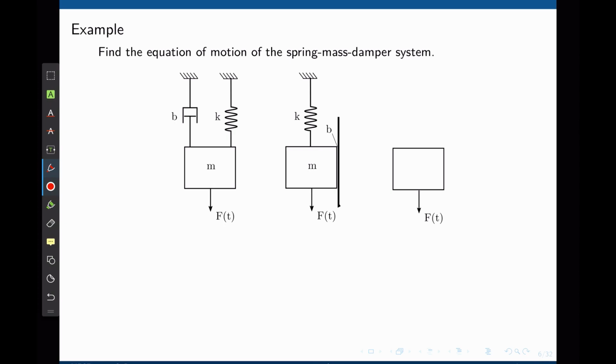The graph on the left is one representation of the viscous friction. The graph in the center is the same representation. In the center, we see that there is viscous friction between the mass and the sliding plane, which is the same as connecting the mass to a damper to a fixed reference frame. These two formulations are exactly the same.